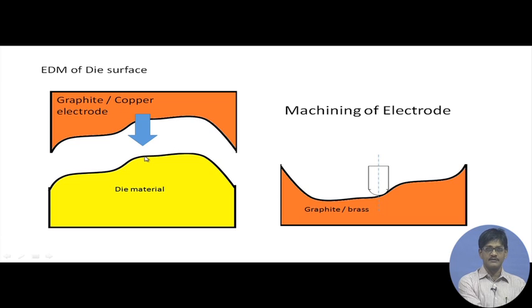So, instead of incurring heavy expenditure due to tooling costs in 3-dimensional machining by conventional machining, by which here I mean removing material from a softer part with the help of a sharp edge, we are employing electrical discharge machining in the die sinking mode and getting the shape on the die material with the help of a copper or graphite electrode.